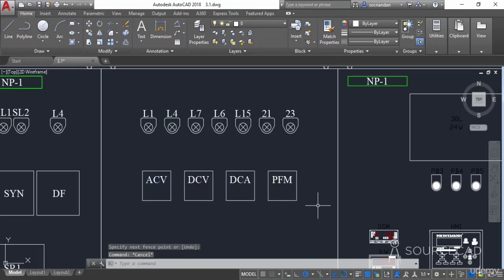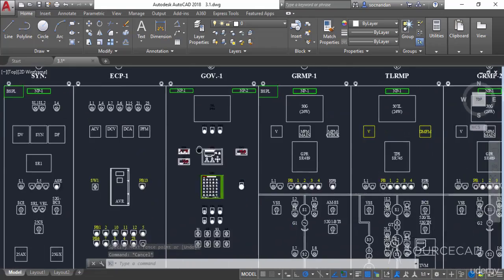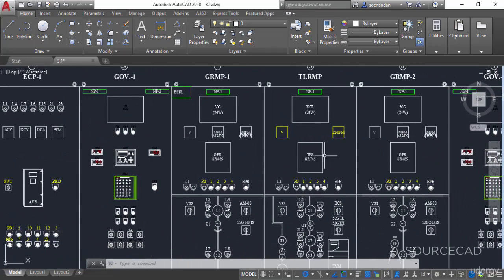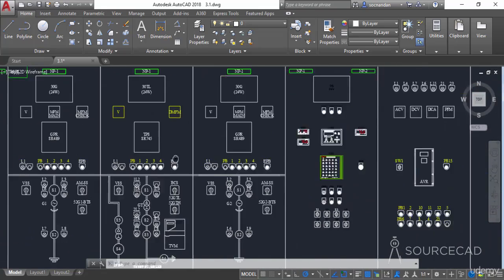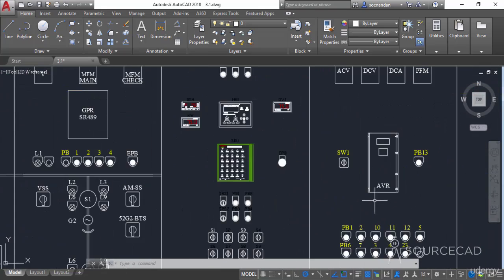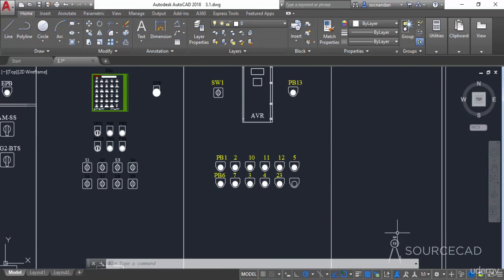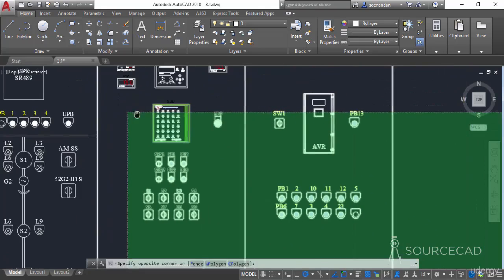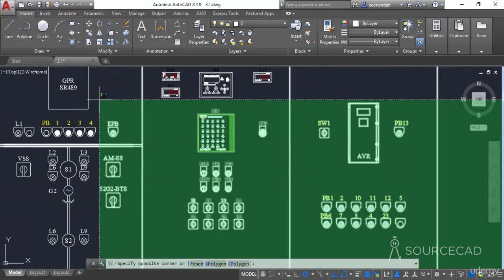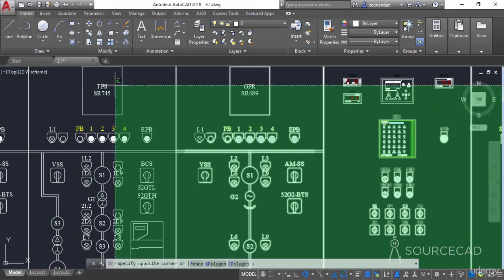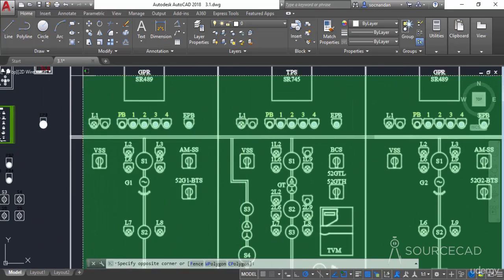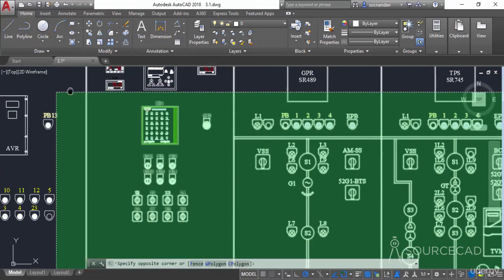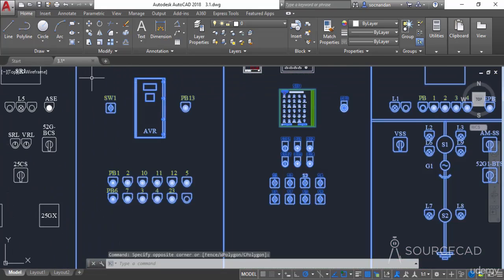In the AutoCAD 2018 version, AutoCAD added an off-screen selection, and the off-screen selection is helpful for selecting long geometries. So let's say that we want to make a selection by zooming this drawing, and we just want to start our selection somewhere from here. Now we are including the objects in our selection set, and along with inclusion of objects, we are also moving the drawing towards the right. We are panning it here, and we are including many objects.